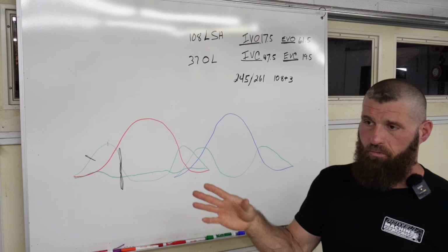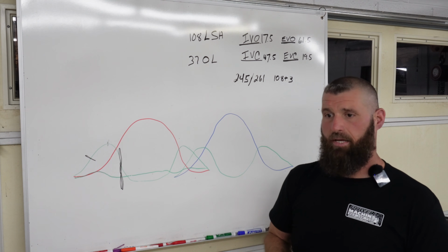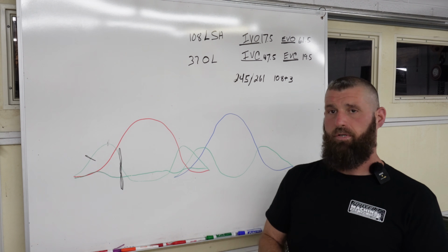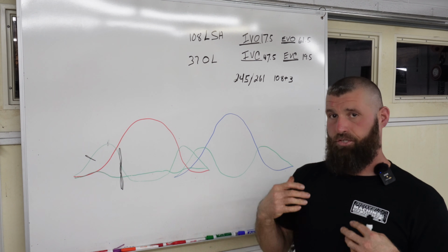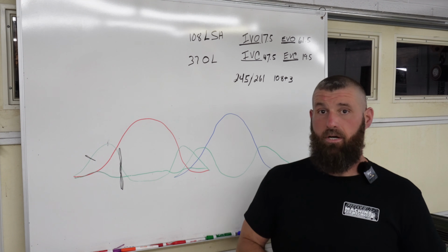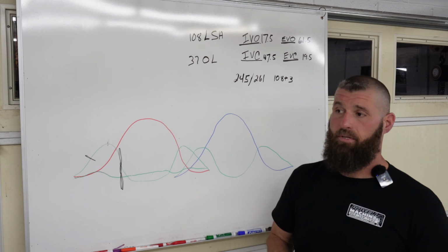So after we crunched the numbers and some other stuff we looked at, and the exhaust flow, and we knew it was going to be in a car with full exhaust, we determined that it needed about 16 degrees, give or take, of overlap, of split in it.